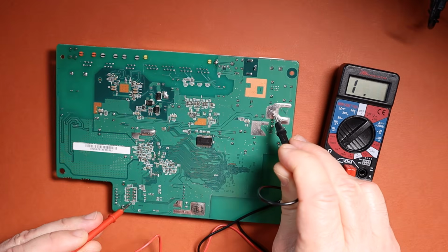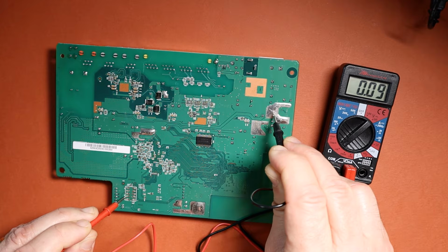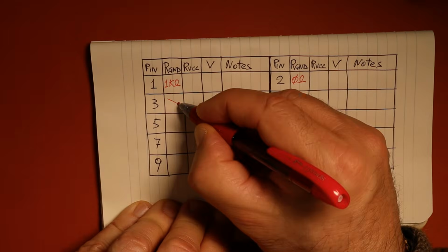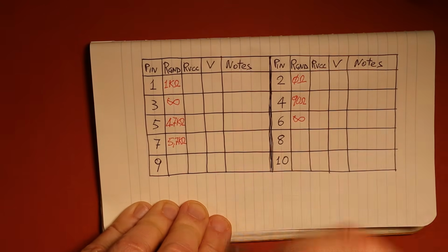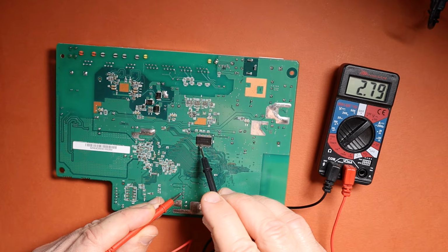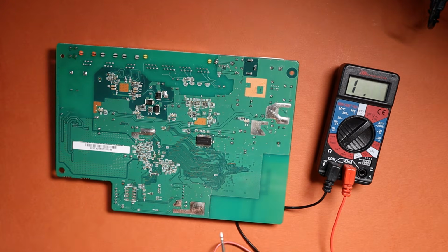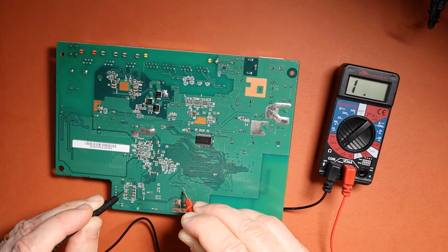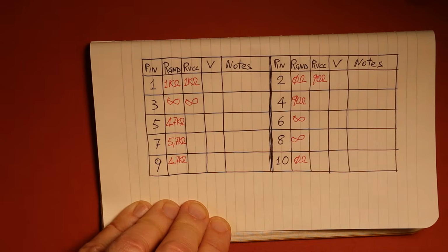With the board powered off, we can start taking resistance measurements against ground, and we start with pin 1, then pin 2, and so on, up to pin 10. We annotate these measurements in a notebook. Then we start taking resistance measurements against VCC. We can get a VCC reference from an integrated circuit on the board and its datasheet. We start with pin 1, then pin 2, and so on up to pin 10, and we annotate these measurements